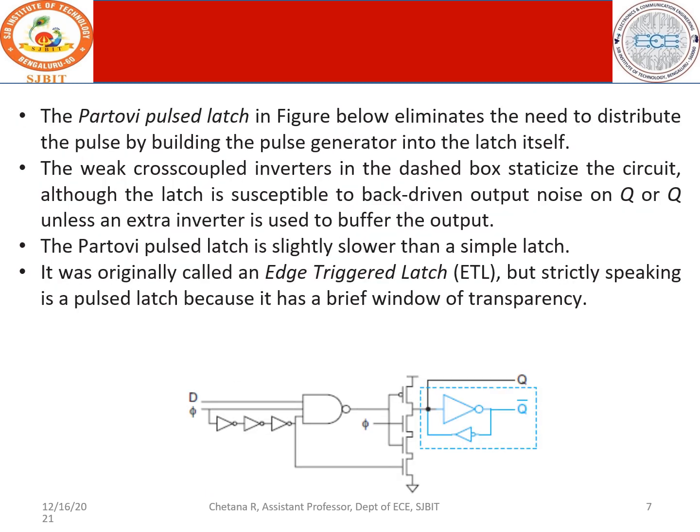Next we have the Partovi pulse latch. This is meant to eliminate the need to distribute the pulse by building the pulse generator into the latch itself. So it eliminates the need to distribute the pulse, since the pulse generator is built in.